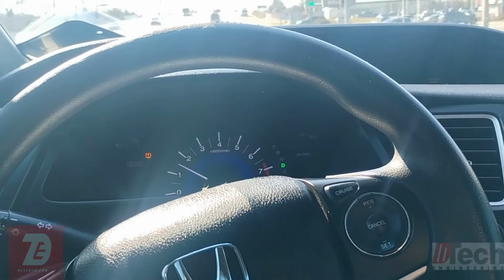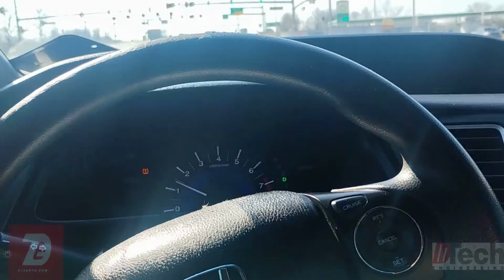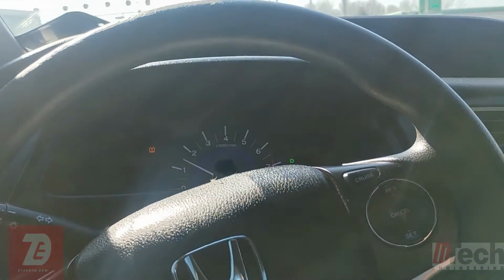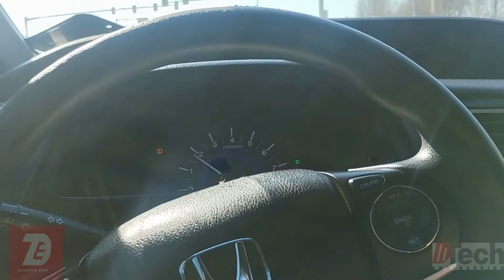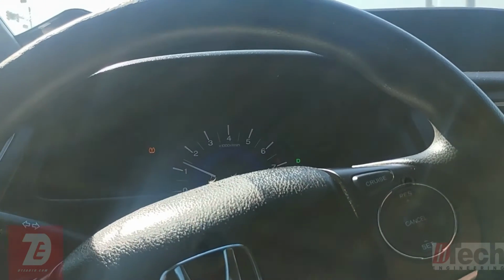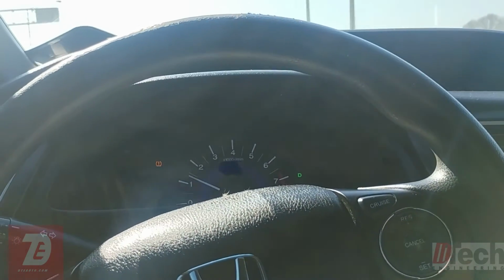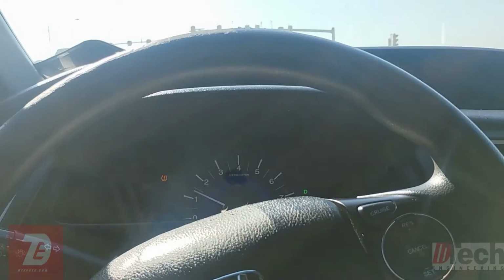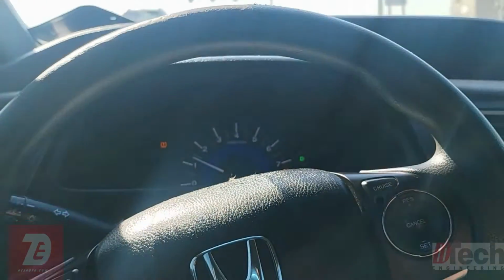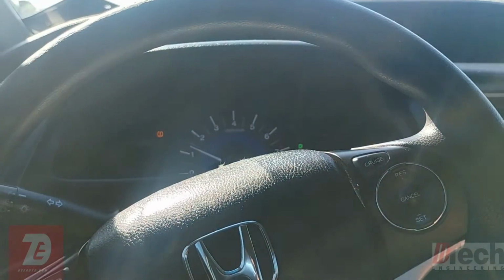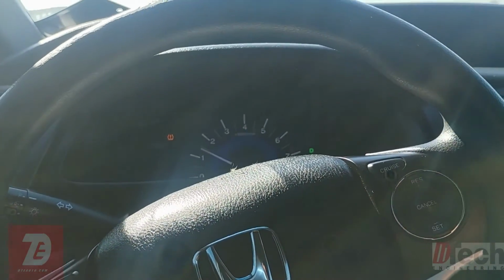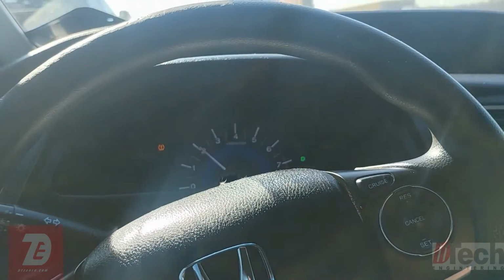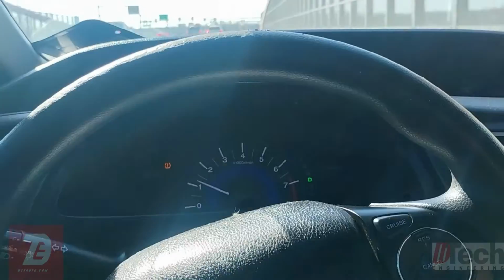That took care of that. But then there was another code for the air-fuel ratio, like a signal not correct, and ended up being just the sensor was not the correct type or style. So I got a factory sensor, installed it, and no more lights. Obviously, tire pressure deal, but yeah, all of that is taken care of, and that's it for this one.